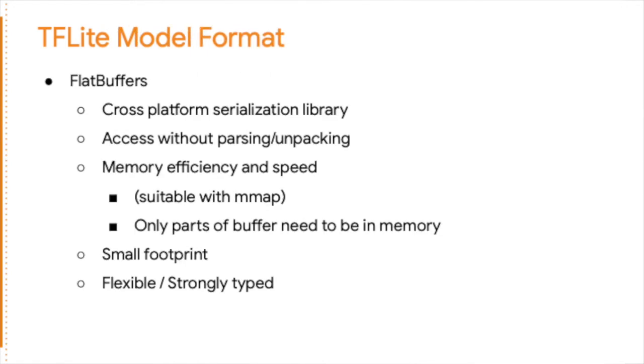And one of the things that I've been very happy about as we've been working on microcontrollers is that we've been using flat buffers for the TensorFlow Lite model format. This is a cross-platform serialization library. You might be wondering, how is this different from something like protobufs? What's really nice about them is that they store their data in a way that doesn't require any parsing or unpacking or copying.